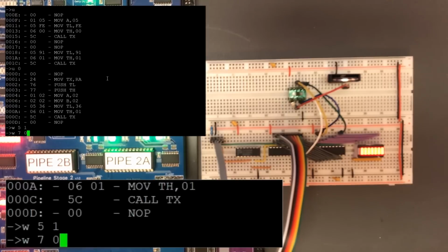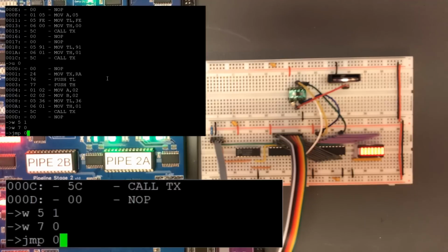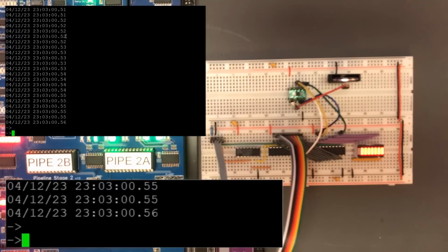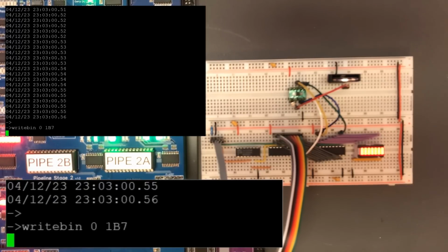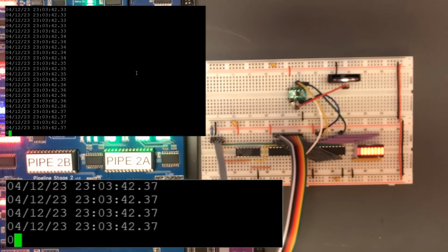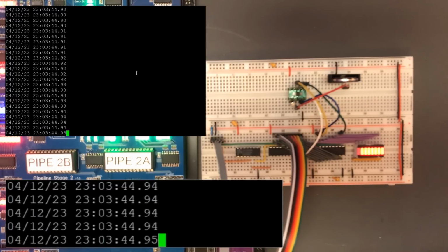So I'm just going to wait till it's exactly 2 minutes past, then reset seconds to 0. Of course, I've made a mistake there and included that write inside the loop. Okay, so it's off by a few seconds there, but that looks like it's keeping time. And if I've done it right with the backup battery, I should be able to turn it all off and have it keep the time.